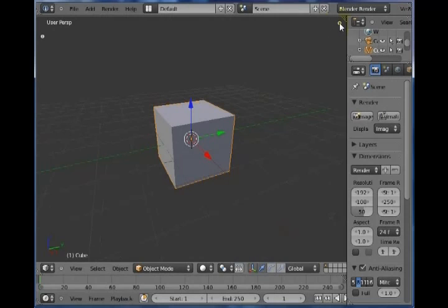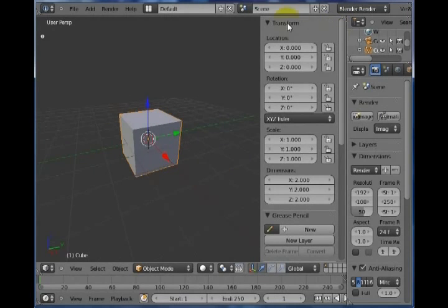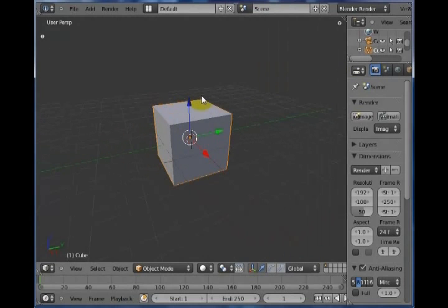And also remember that you can press this button to look at the transform properties of the object. I can actually scale or change the location of an object in here right within these settings to be a little bit more accurate than just hitting S to scale, G to grab, and so on within the menu.